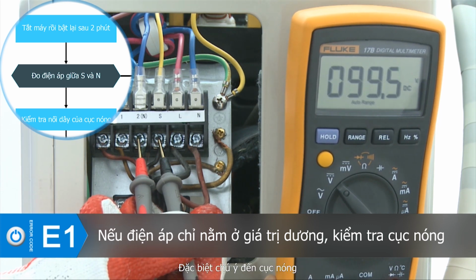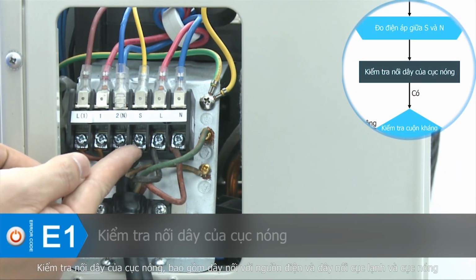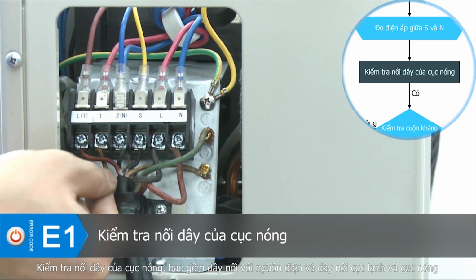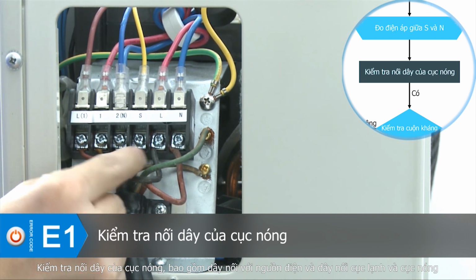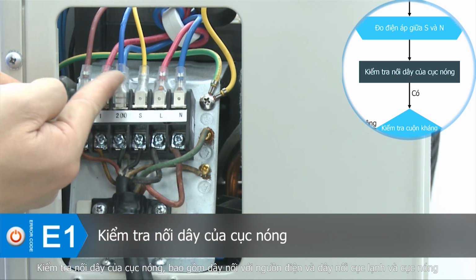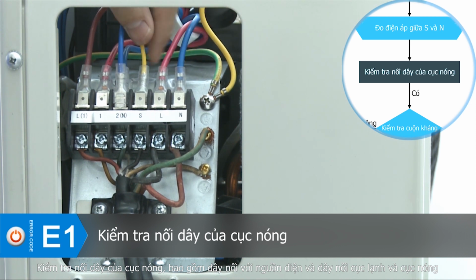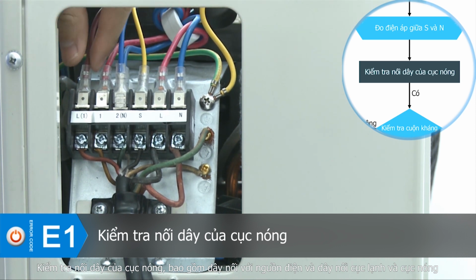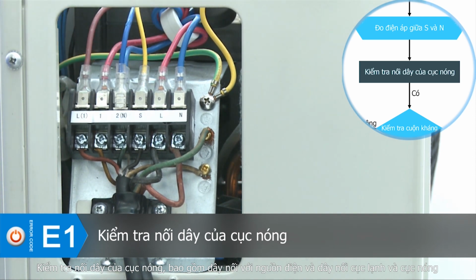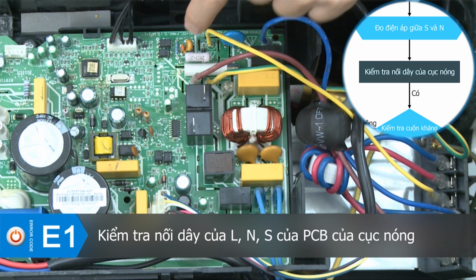Main attention should be paid to the outdoor unit. Check the wiring of the outdoor unit, which includes the power wires and the connecting wires between the indoor and the outdoor unit. Check the wiring of L and S of the outdoor PCB.